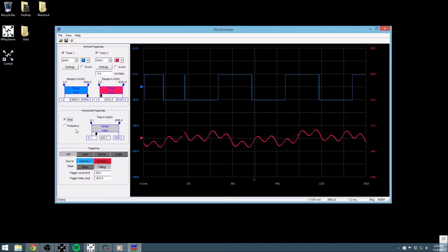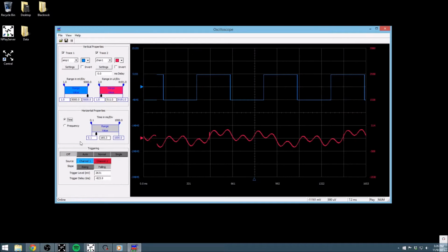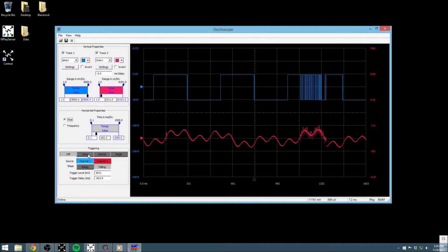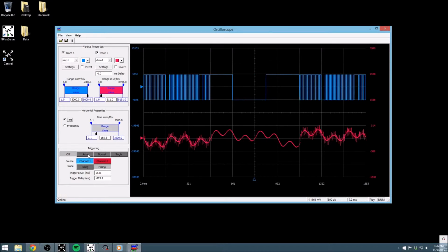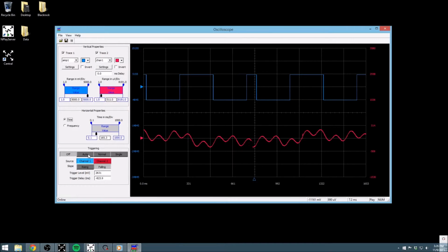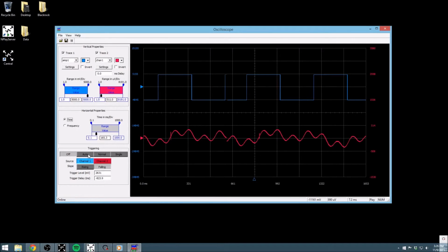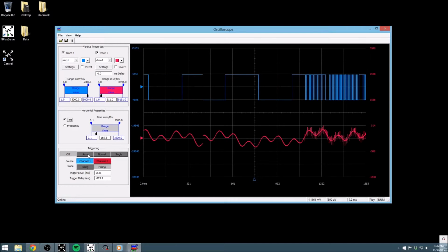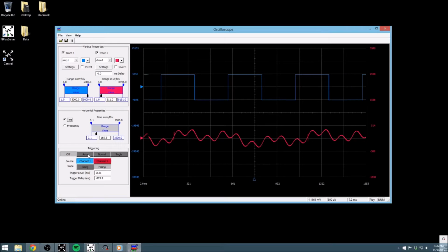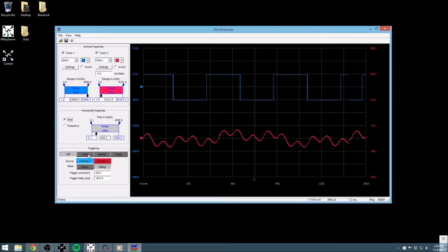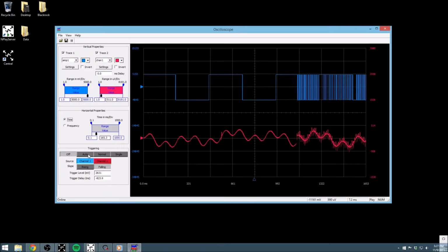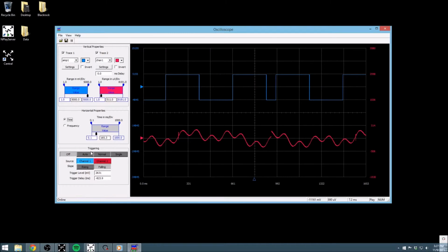If we go back to the standard trace by selecting time, we can see another common use of the oscilloscope, the triggering feature. Triggering allows us to focus on a piece of our signal based on a threshold crossing. A very common setup for the triggering feature is to use a pulse on the analog inputs as the trigger to observe what happens to a given neural channel shortly after some sort of stimulus presentation. I'm just using sample data, but we can still use it to show the usefulness of the trigger features.